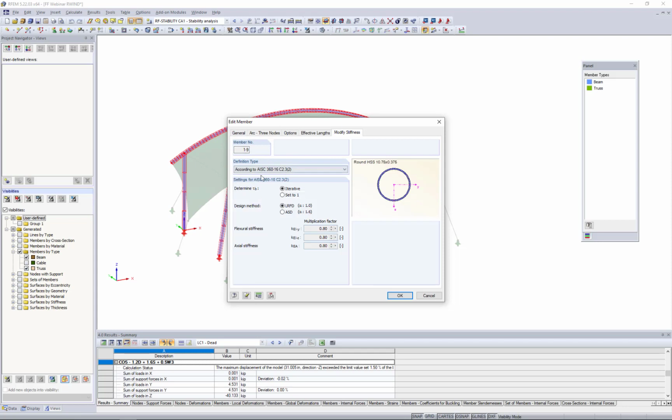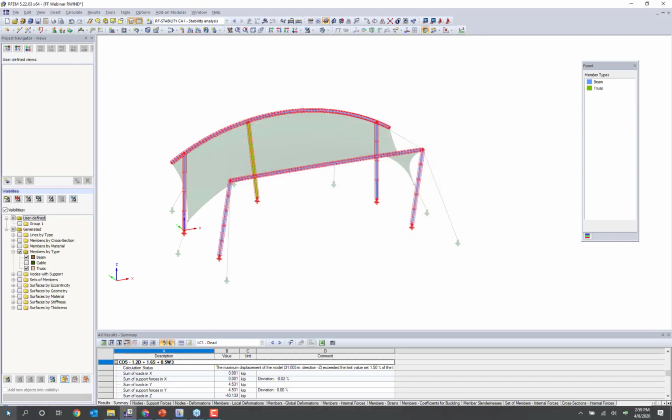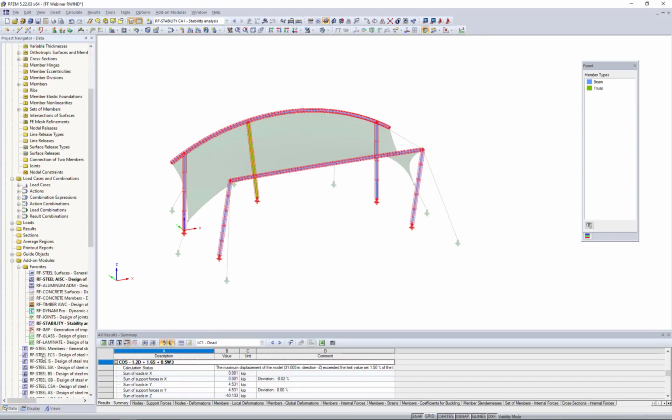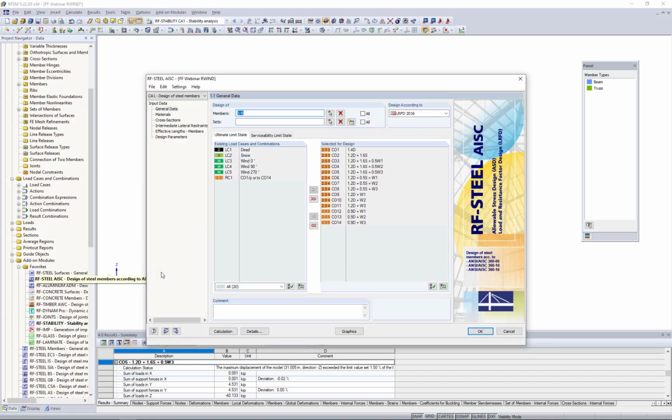This is going to apply a tau sub B stiffness reduction as well as the multiplication factor 0.8 to our flexural and axial stiffness. Again, this is just required per the standard, Chapter C, when we are designing per the direct analysis method. Those previous webinars that I mentioned really give quite a bit more information on the background of that. So just briefly touching on that.